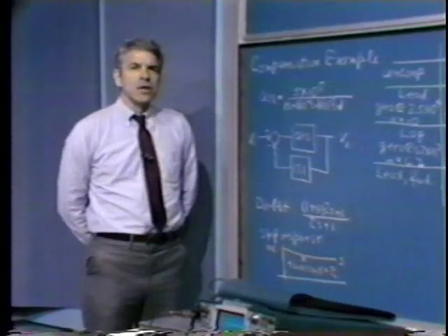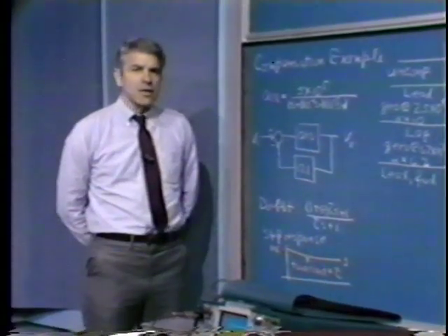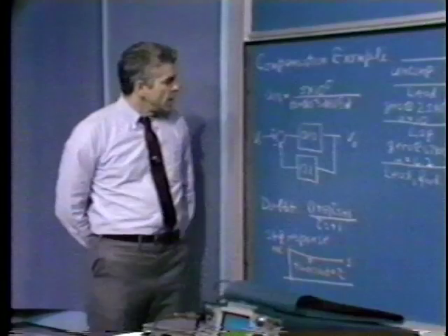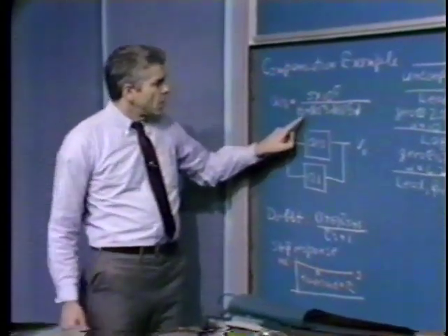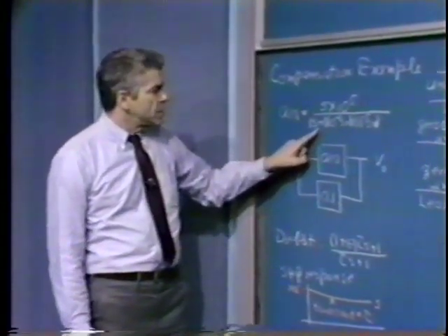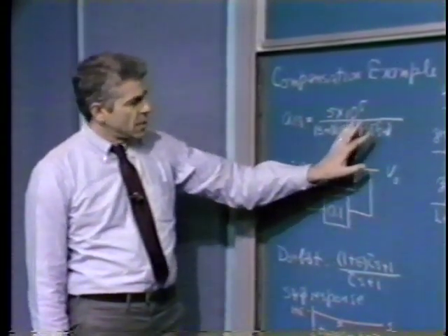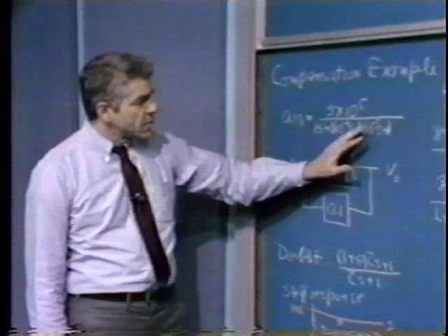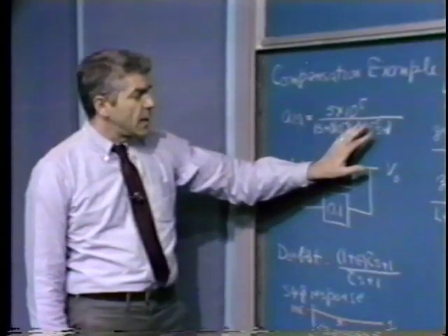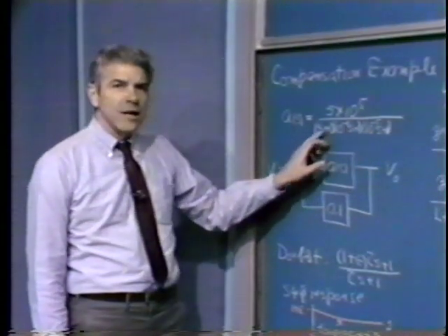I'd like to say a little bit about the choice of transfer function. The general form, where we have one very low frequency pole and then some higher frequency things that begin to give us additional negative phase shift at higher frequency, is a very, very common pattern.